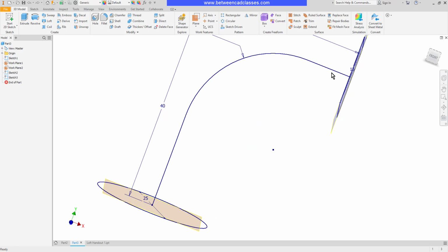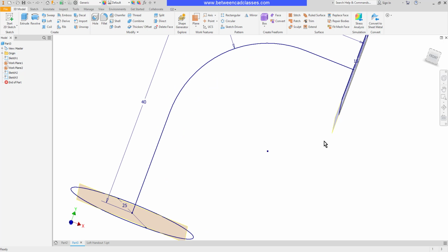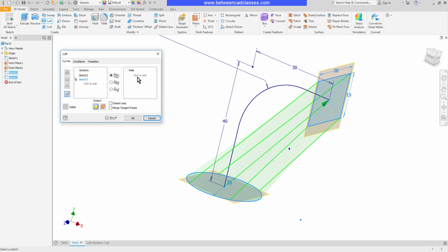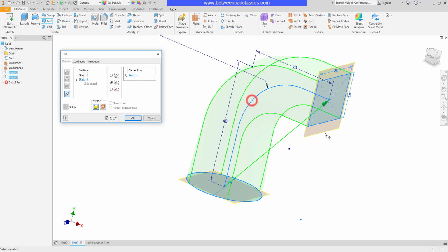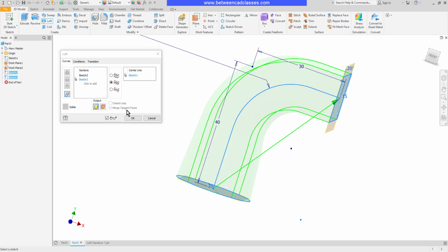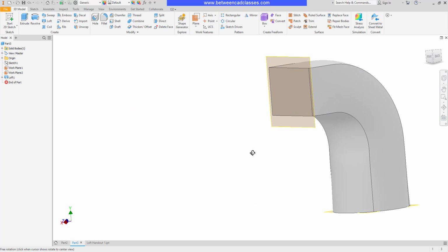The other thing that we can do is use a rail. So I've already got this sketch in here, basically like a sweep. I'm going to come back with the Loft tool, select my two planes here. Then over here on the right, I'm going to click to add a rail, and I'll select this sketch shape here. Now you can see it disappears, and that's because of these options right here in the middle. The default option is for the rails to be along the outside of the shape. I want the one that's going to be in the center of the shape based upon how I sketched these items. I'll go ahead and select my shape again here. And now you can see that I'm going to get a blend between the two shapes while it is sweeping along that sketched path.